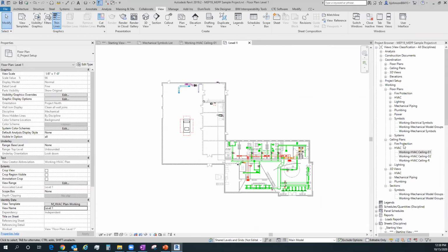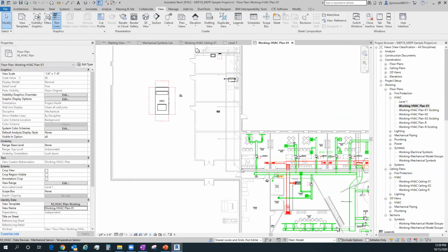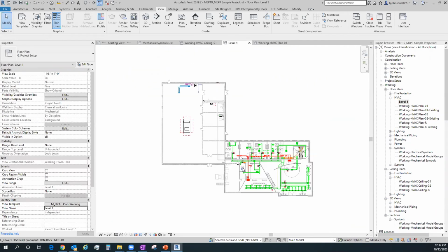Actually, I did floor plan instead of ceiling plan, so it's not going to show up the same. But within this view, if my floor plan version should be this guy, if this one was the one that had the problem and I reapplied my new template to this new one that's called level 1, then if there was something missing in the previous one here, I should be able to have a freshly restored view with a new view template applied correctly. So if that was a corrupt view, I could just pick in it, do a copy, and then click out of it, delete it, and then pick in here, do my naming convention, Control V, have a fresh new view, and then be off and running again, no problem whatsoever.